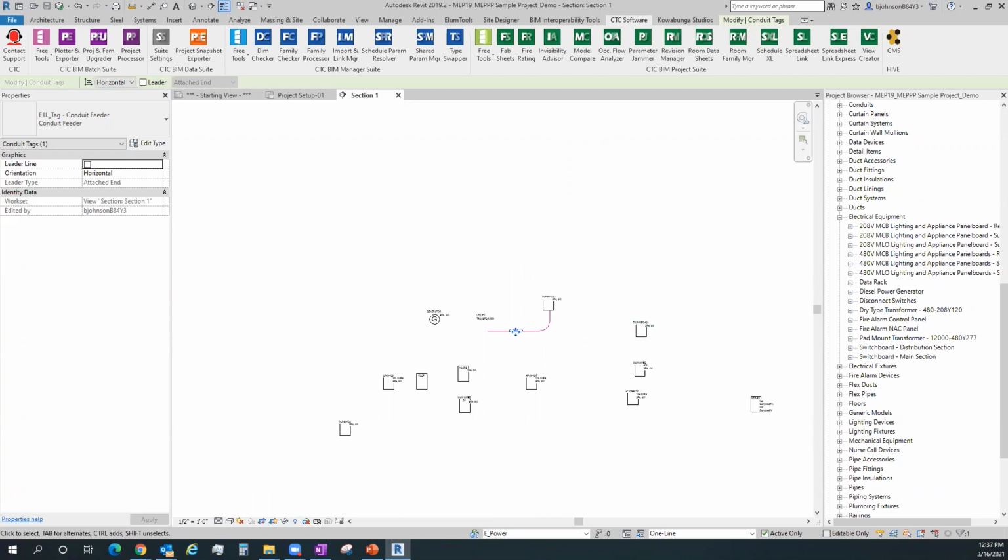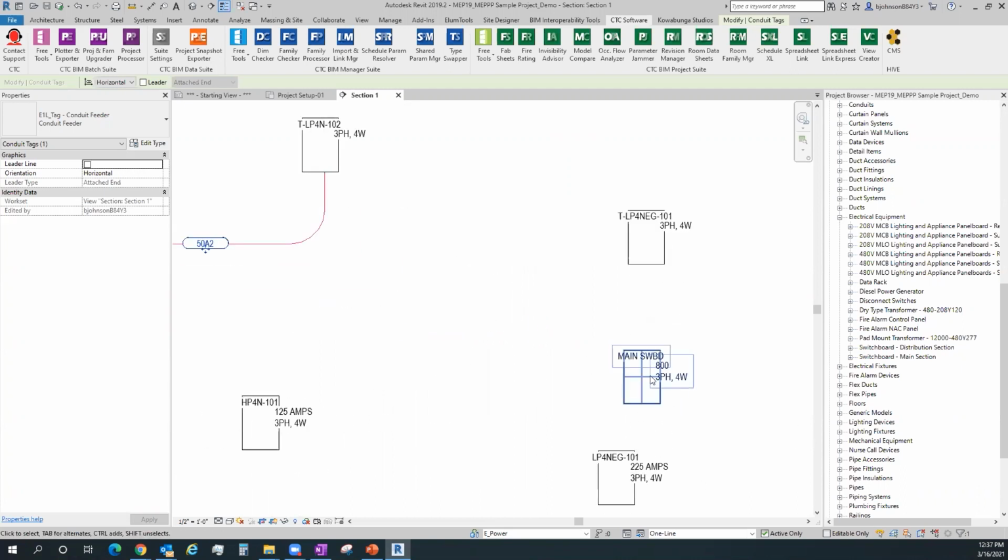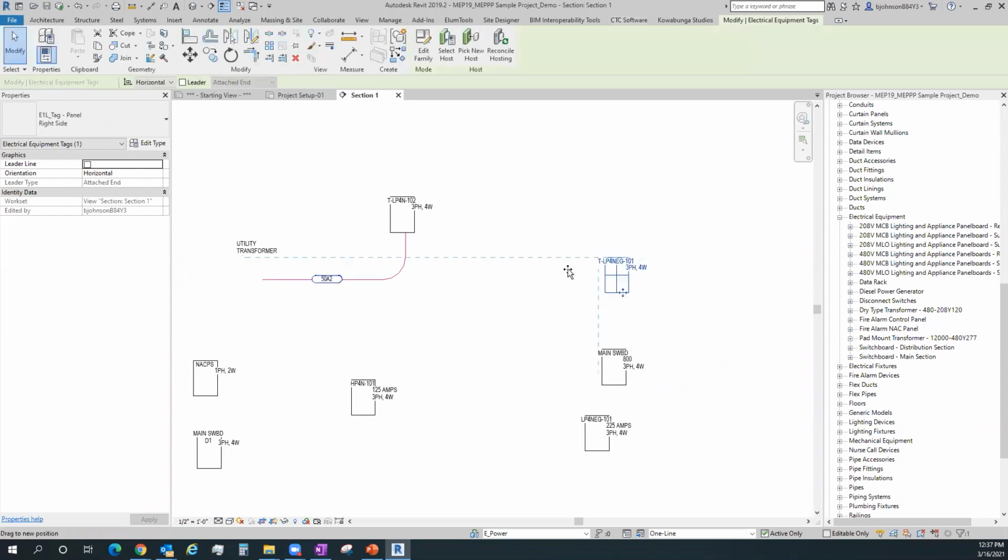How do you move the text so it's in line? Letter tags? I'm not sure if that's just meaning to edit the family. So in other words, if this is overriding my line work or something like that, I would just go into the family itself in the tag and just move those labels to where they need to go, whether you want it left side, right side, bottom. But the components themselves, if you move them, they will track with other components. So they do show up kind of in line with each other based on their references from their endpoints of text lines and things like that, right? If it's the box itself, it tries to line up center to center in those cases. So if I want to draw it straight across, I can do those.